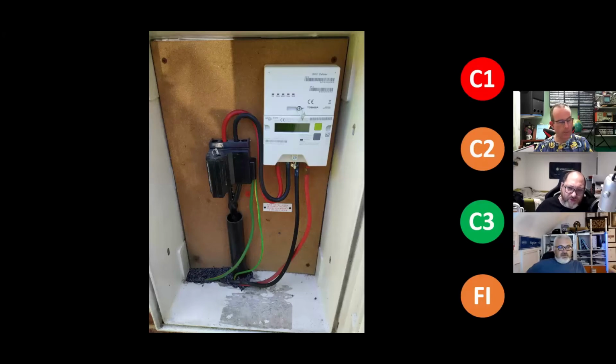So it's evidently PME. It's on the red phase, so it's obviously a PME on a new estate, telling somebody it's on the red phase, which is what they used to do. But maybe that's a local electrode. Maybe that's the end of line. Is this another end of line one? No, it isn't actually. What that is, the thin one is the earth to the consumer unit, and then the bigger one is to the gas meter, which is fairly adjacent as well.